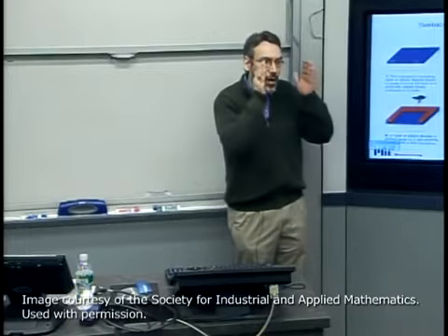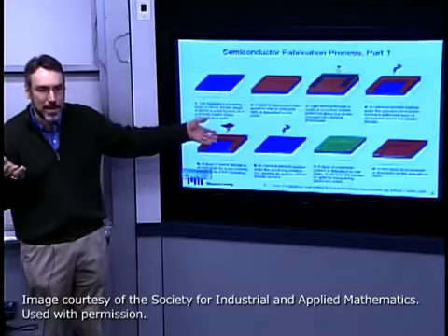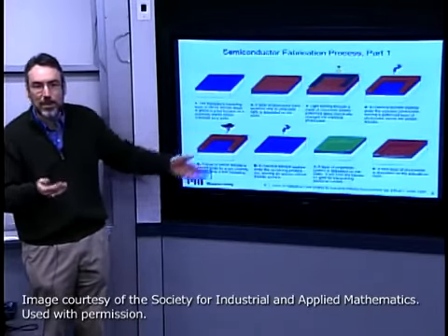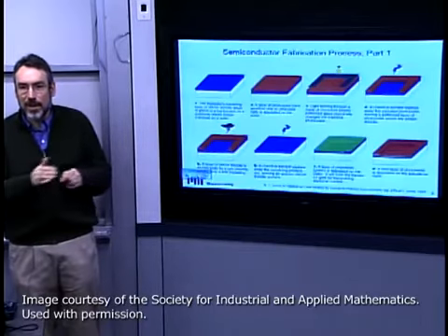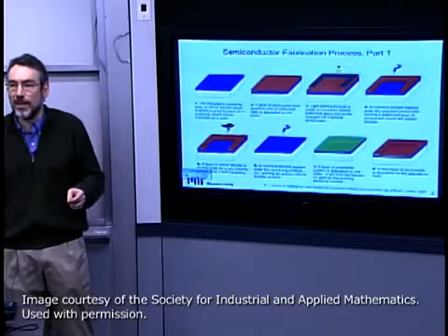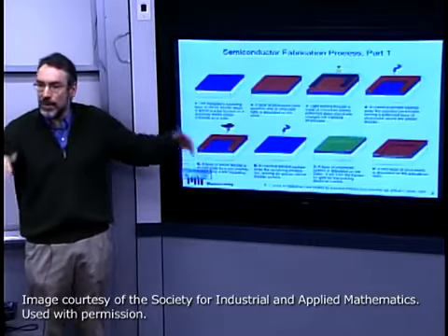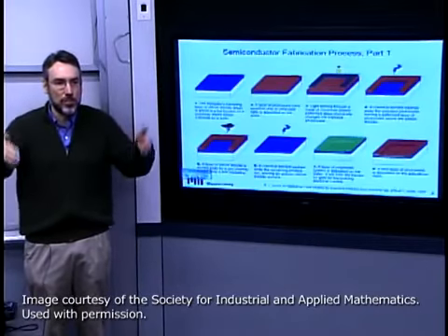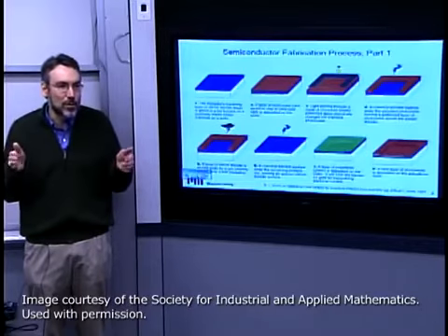You don't even have to try to set up a timed etch. If I was etching at 1,000 angstroms a minute and I started with 5,000 angstroms, I might etch for 5 minutes. But to be sure that I've got the same degree of uniformity everywhere, I might etch for an extra 10 seconds. That way I'm sure that I'm clearing everywhere across the wafer, even if there's spatial non-uniformity in my etch, or today's etch is etching slightly slower than yesterday's.